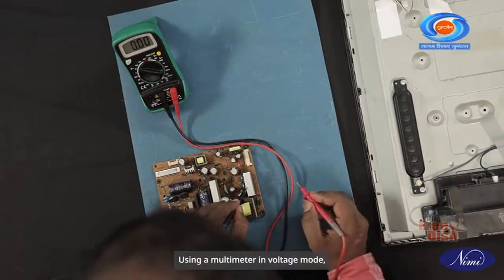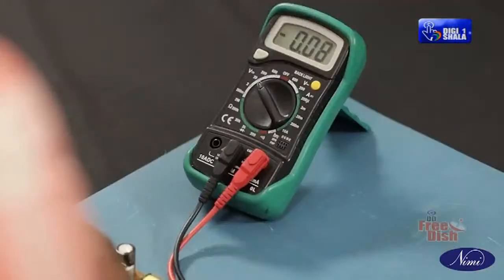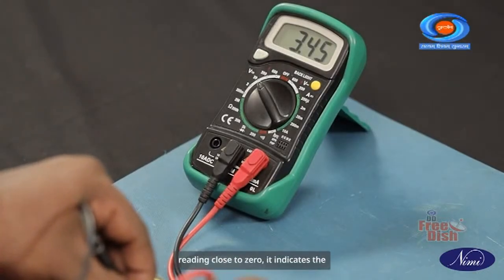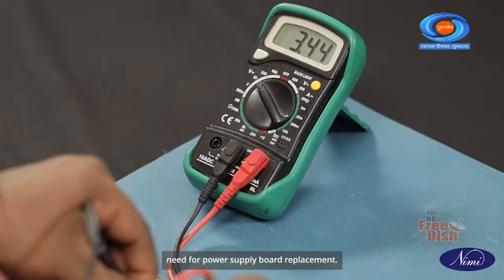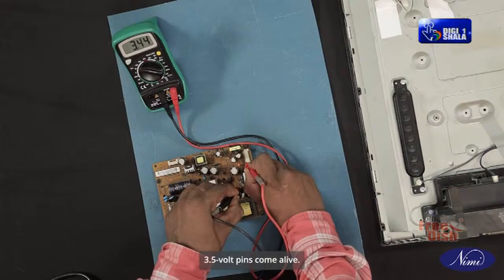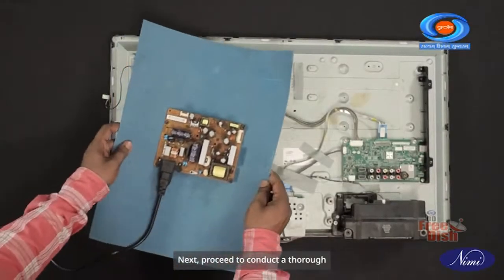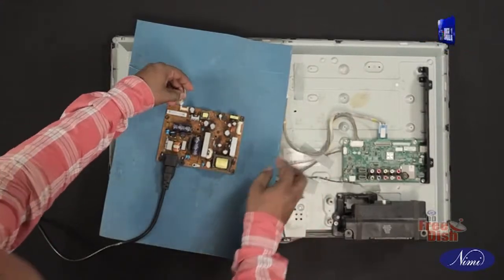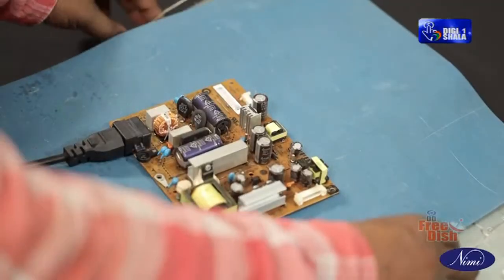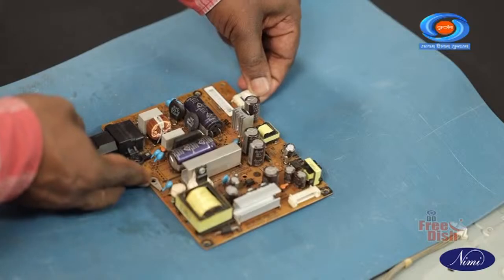Using a multimeter in voltage mode, place the probes on each terminal of the power supply board and carefully record the readings. If any terminal shows a voltage reading close to 0, it indicates the need for power supply board replacement. In power supply board testing, only 3.5 volt pins come alive. Next, proceed to conduct a thorough inspection of the main board. Connect the main board and backlight cables to the power supply boards. Then connect the AC socket to the power supply and switch it on.